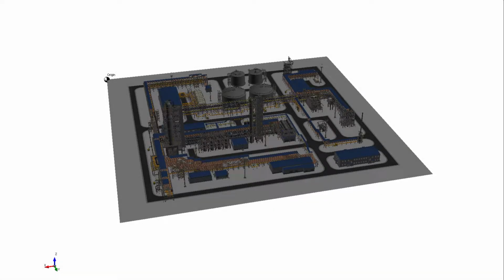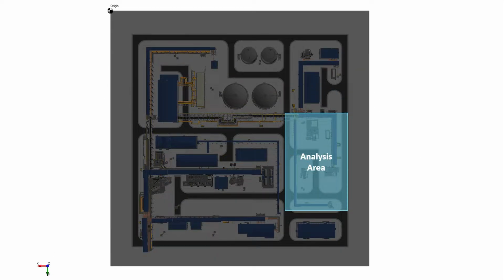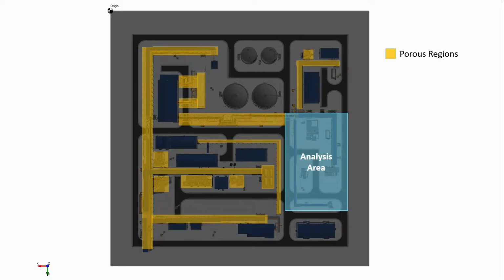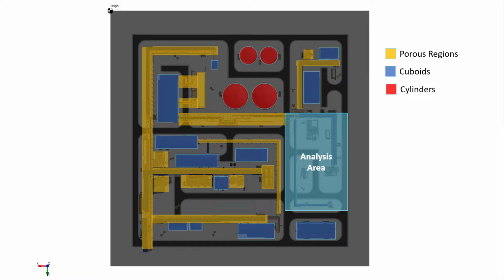Although using the full CAD model provides a more accurate result, it can lead to longer computation times. For larger projects, it may be beneficial to replace far-field CAD items, which are away from the analysis area, with volume-based porous regions or primitive shapes with the CAD creation tool. This approach is commonly used across the CFD industry, and not just with the Flux CFD software.